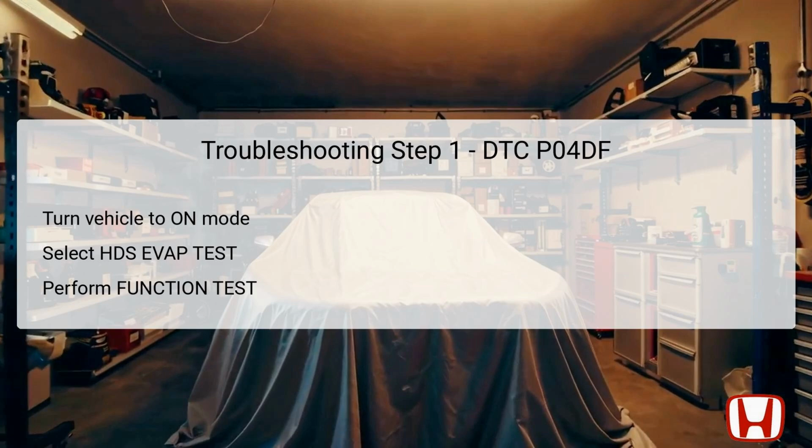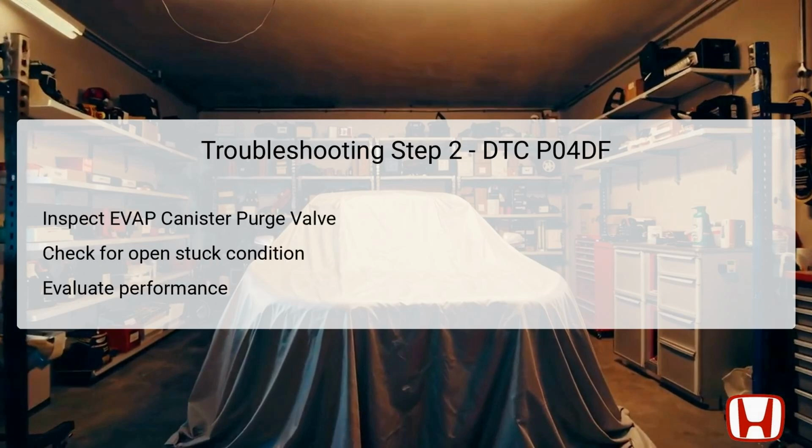These initial tests are crucial for duplicating any identified failures before proceeding further. Following the diagnostic testing, the second step involves a thorough inspection of the EVAP canister purge valve, a critical component in the system. First, assess the valve to check if it remains open or stuck in any position, which can lead to abnormal vapor flow.